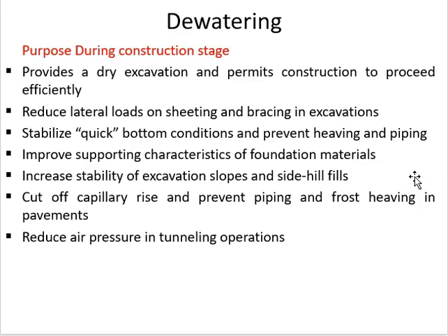So the purpose of dewatering during the construction stage is to provide a drying platform to work, reduce the lateral pressure on the bracings in excavations, increase the strength of soil due to reduction in the pore water pressure, increase the slope stability, prevent seepage problems such as piping, and also reduce the air pressure in tunneling operations.